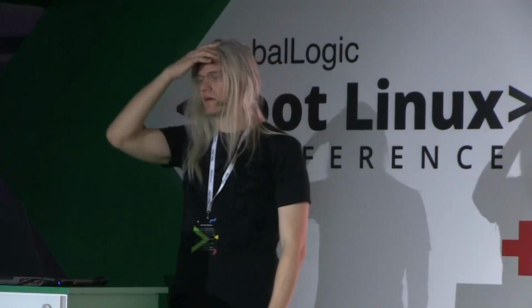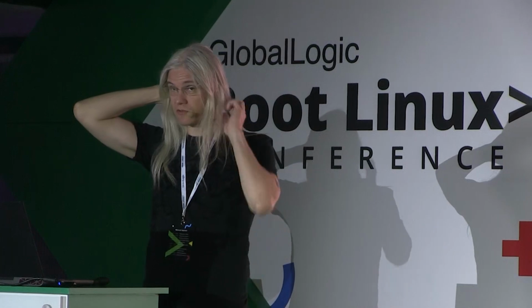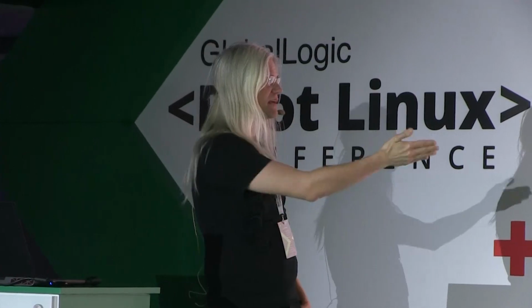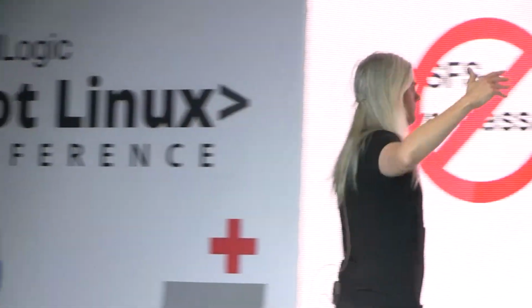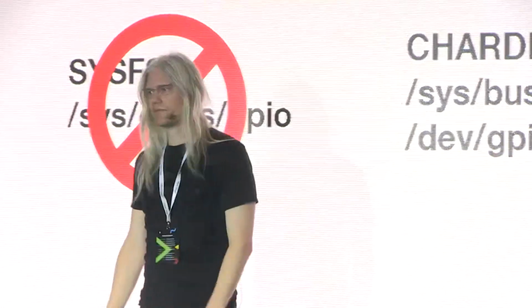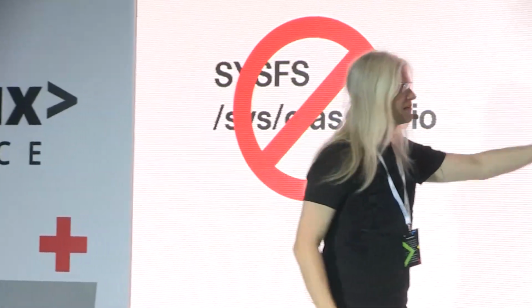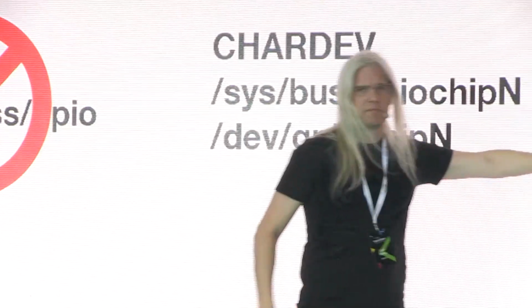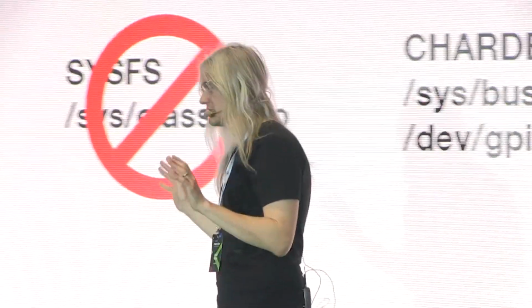Normally, you should not control GPIOs from user space. A lot of people do it, and those are the automation cases that I showed you on the first slide. You know, all automatic control and so on. Makers, builders, and so on. They want to control GPIOs from user space, and then they should use /dev/gpiochipN. And we have made some nice example tools, and there is libgpiod that helps you to do this the right way.